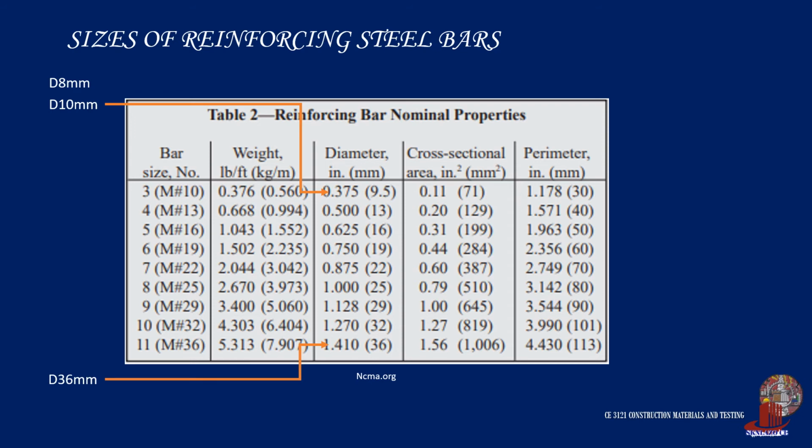The commercial lengths of rebars would start from 5 meters, although this length is not much available. 6 meters is the most commercially available length, along with 7.5 meters. Longer lengths can still be bought through orders, that is 9 meters, 10.5, 12 meters, and 13.5 meters. Note that the lengths would have an interval of 1.5 meters.